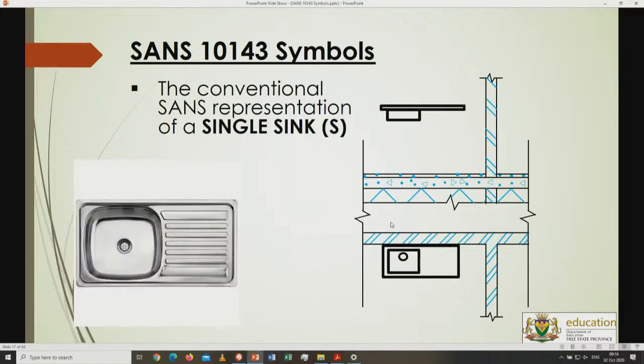All right, this is now for a sink. For a single sink itself, you can see again it has got lots of detail. You can see the lines, you can see the curves and all those types of things. None of that needs to be shown. And then so many times learners go and make from that point over there where you put the flat area, you basically don't show any lines over there. It's just a rectangle inside, and then a circle. From the front view itself, this will be seen as the level where the cabinets will be.